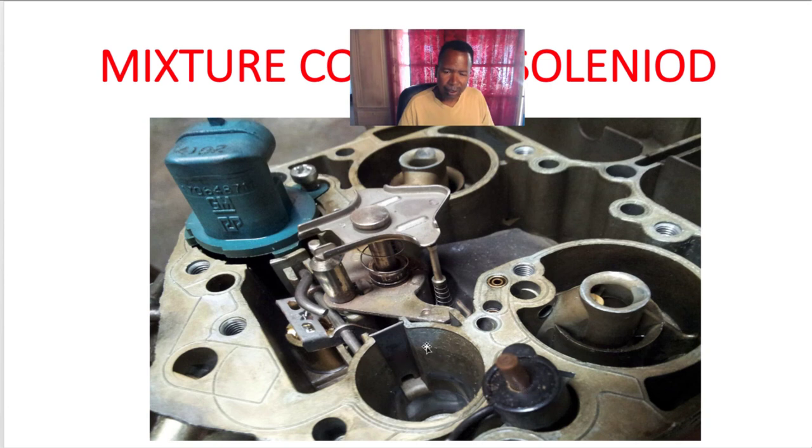Here's the TPS. Here is the accelerator pump well we talked about earlier. Here's your float. This is the fuel bowl right here. That's the float. Here's the needle and seat over here that lets the fuel in. And here's the main metering discharge nozzles, which we talked about earlier. You can really see it now. And the accelerator pump discharge nozzles are over here somewhere. You can't see it. There's two of them, one here and one over there.